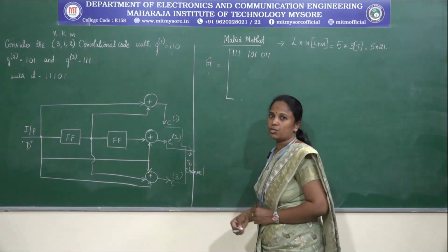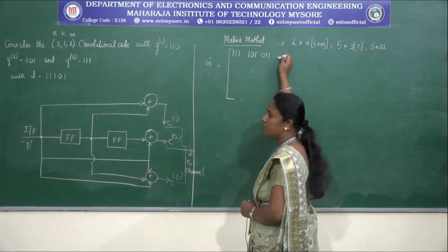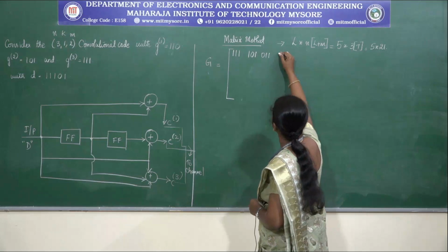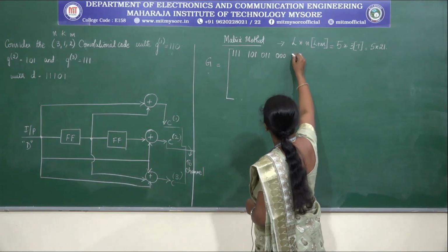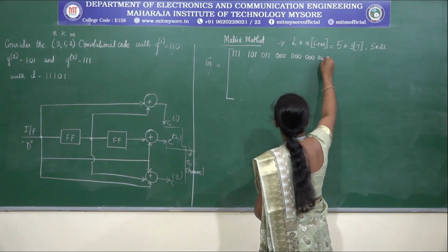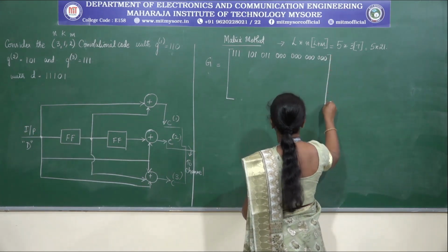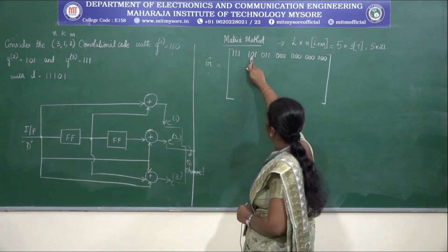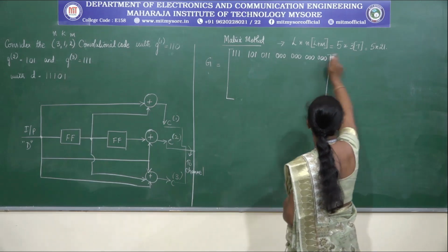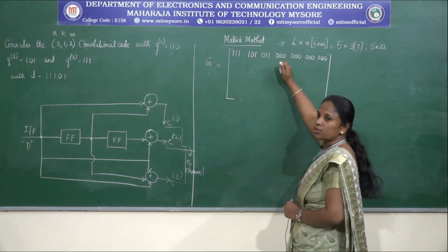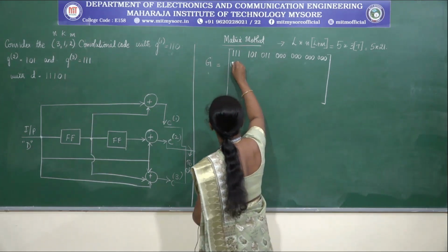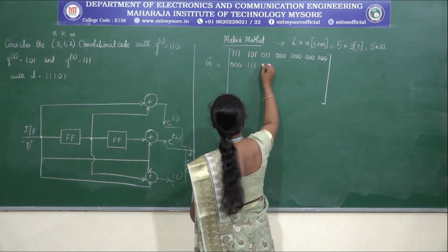So what should we do with respect to the next bits here? They are replaced by zeros. So now we have 9 bits, and the rest of what we should get is 21 columns. So the rest of the bits are represented by zeros. So now fill this generator polynomial.